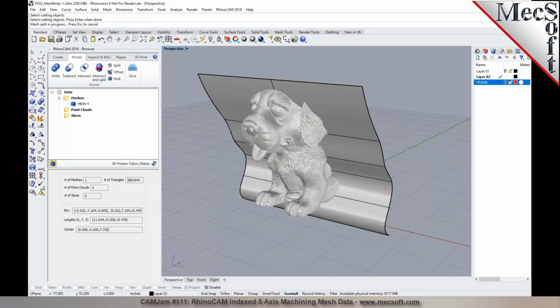So there's different ways how you can do it. I could have converted this surface, what I created, to mesh and used the intersect and split command in the mesh module. So there's different tools, different ways how we can accomplish it. I see. Yeah, so it doesn't necessarily have to be a mesh when you're using some of the Rhino tools. Like you can even split it with just a curve segment or curve geometry.